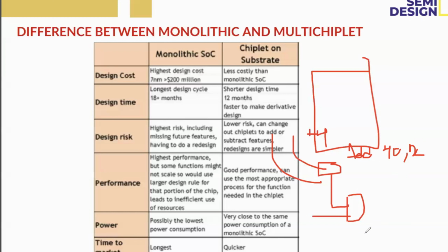There will be internal ALUs. From that it will send to the decoder. Why a decoder? Because this is the instruction we are telling the processor to do, but the internal processor will not understand the instruction, right? The internal processor can understand only binary. So this instruction will be decoded here.